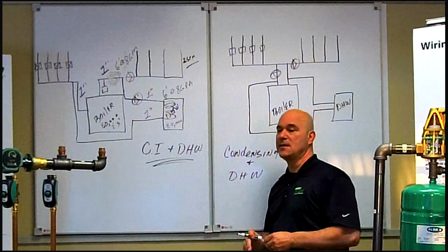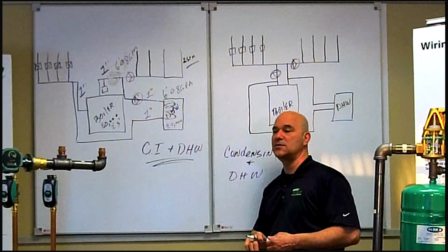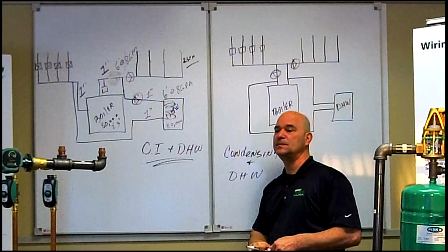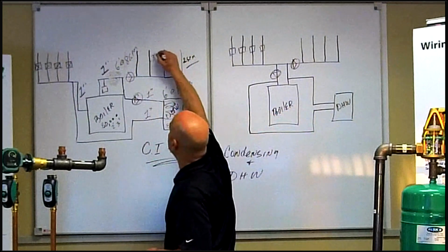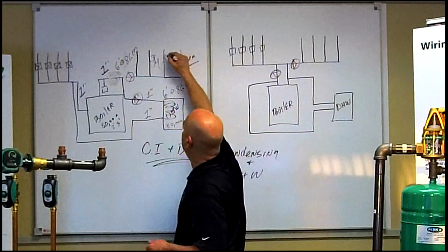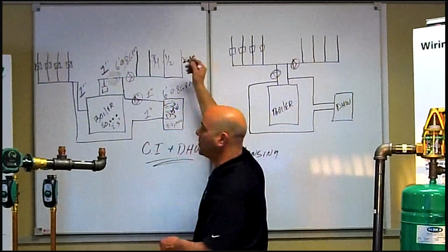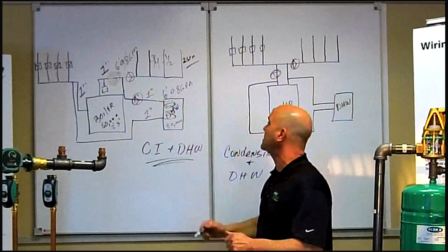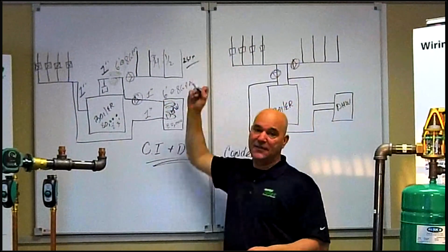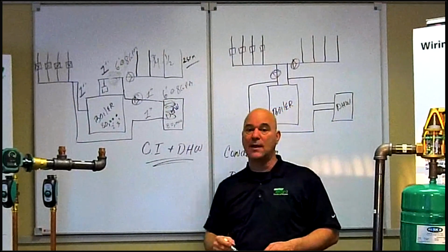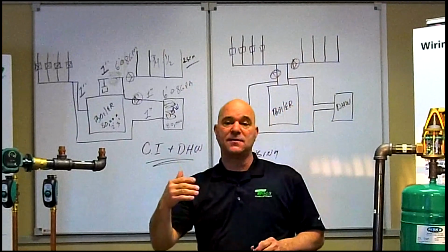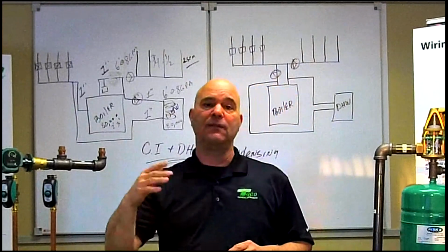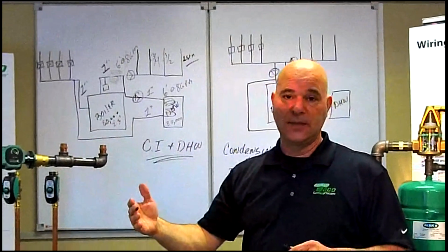Heat circuit piping size, anybody send you what size that should be? 1/2 inch or 3/4. I came in from Peter. Beautiful. 3/4 from Richard. Most common you're going to see out there is 3/4, but if you look at your chart, and we do this on purpose to make you guys think outside the box a little bit, it could be 1/2 inch, but we know in all reality, more than likely, that's going to be 3/4. And then we will utilize the TACO switching relay to give us priority hot water.